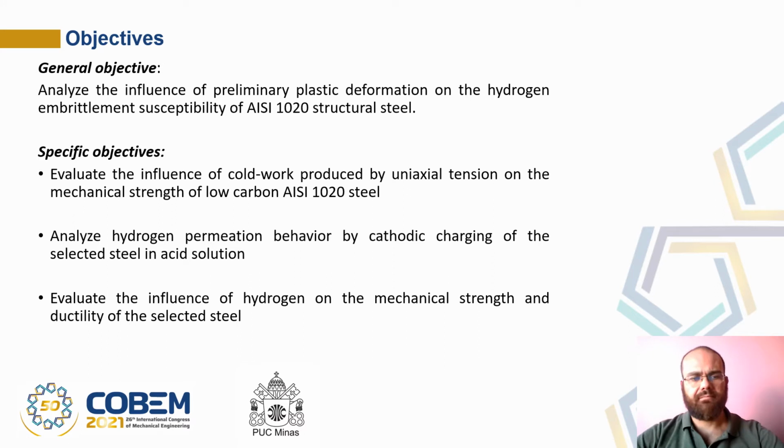So, based on these premises and based on the fact that structural steels are used in a variety of conditions, we proposed to analyze the influence of preliminary plastic deformation or pre-strain on the susceptibility to hydrogen embrittlement of a structural steel, a common 1020 steel, low carbon steel.